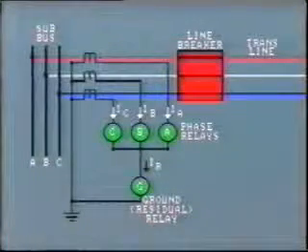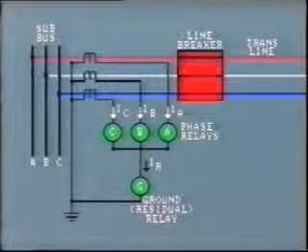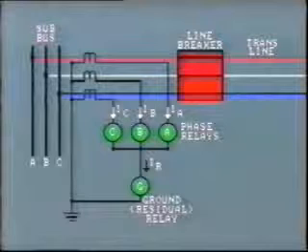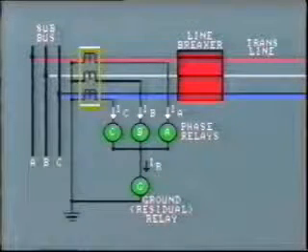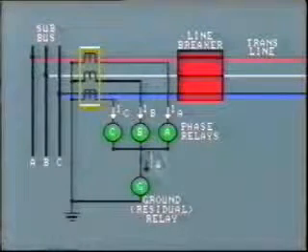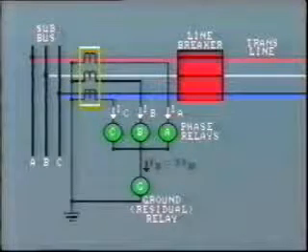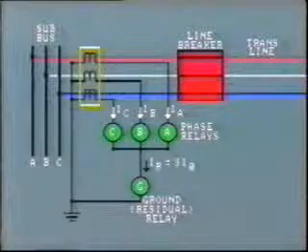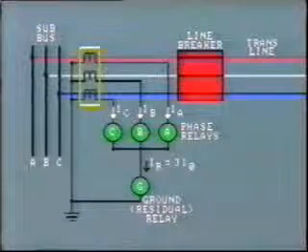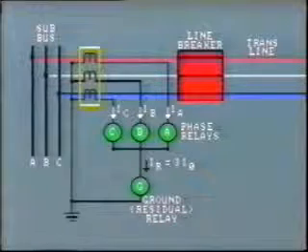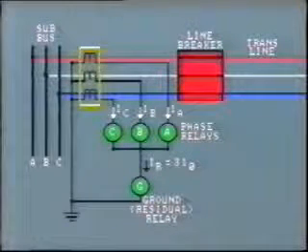However, every major transmission line should have its residual current monitored. Where CTs are Y-connected like this, we can conveniently measure residual current or 3I0 current in the neutral return circuit. These are the same CTs that provide input to the protective relays for line protection.